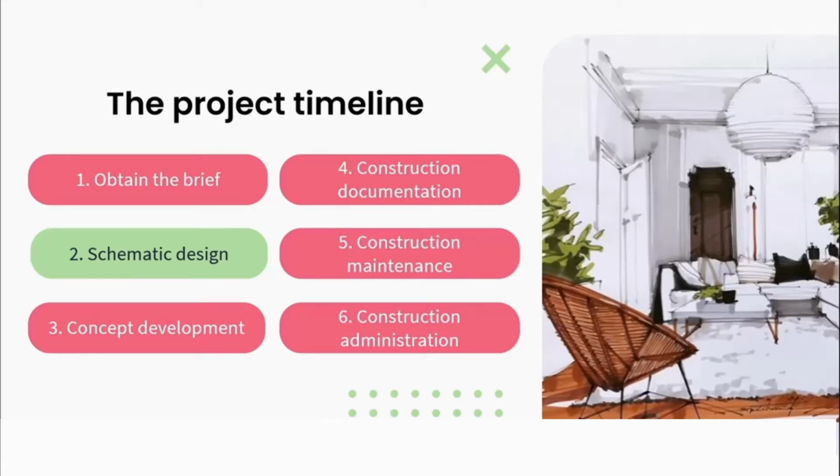From here, your next point of call is the site survey. So technically, you would do your site survey right at the beginning phase of schematic design. You would make an appointment with your client, explain to them your process relating to your site survey, and then go and conduct your site survey in person on that site.